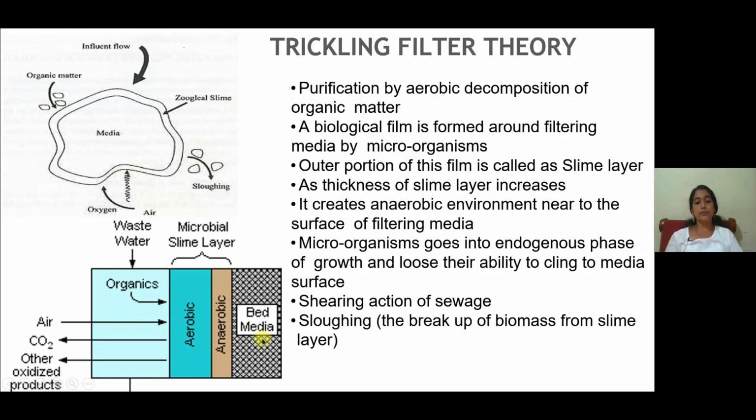This is because first the sand particles or the filtration materials will form a slime layer around the surface of their particles. Then it will allow the microorganisms to grow in that slime layer. If the thickness of this slime layer increases, then the aerobic condition will not occur. Then the anaerobic conditions persist, and it will decompose the organic matter through anaerobic decomposition.